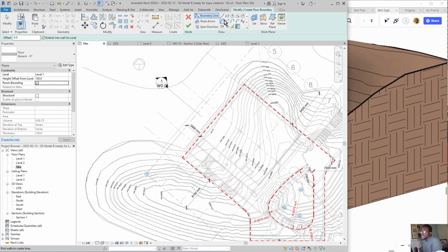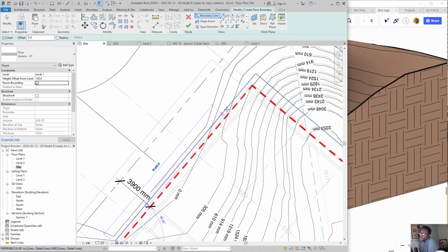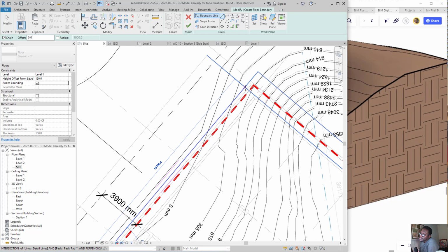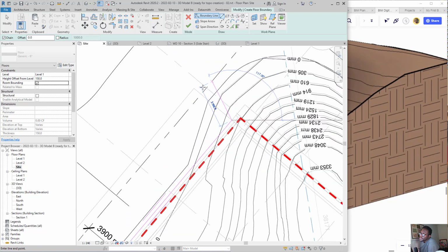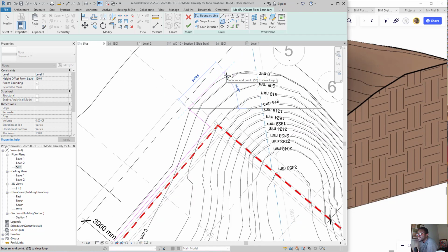And then we're going to use, well, I'm actually going to draw this out. So I'm going to put my line tool like that, and up there I'm going to click a 3-point curve to get these curves going.